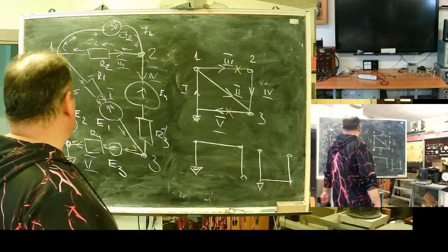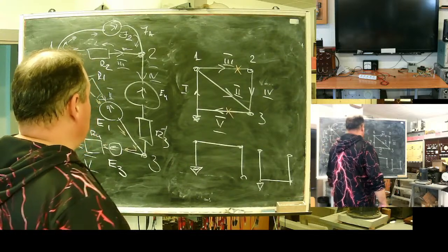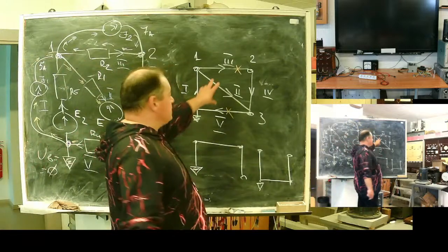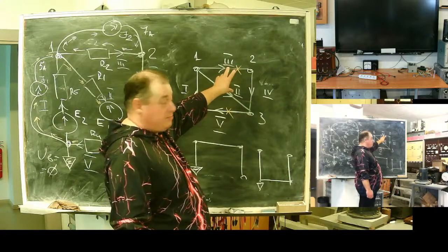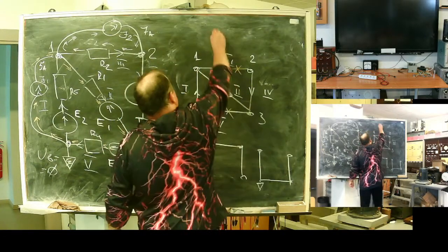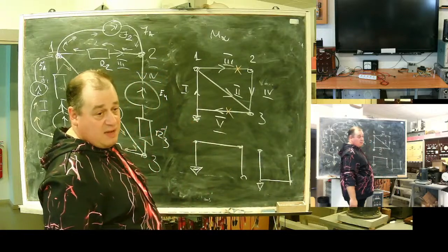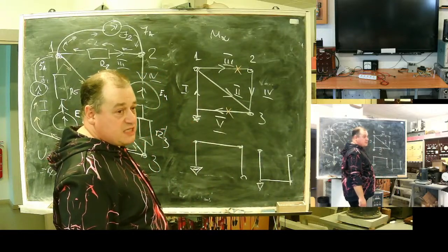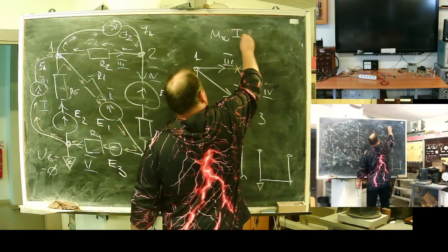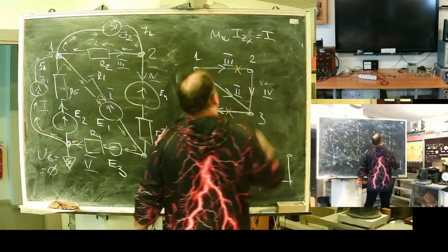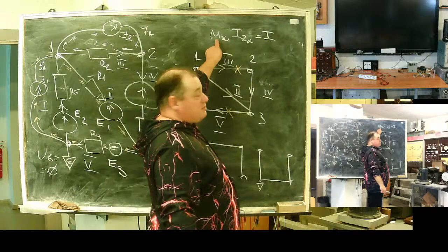To keep my graph connected. And here is one important moment. Actually, this graph represents some form of reduced schematic. This schematic can be described with the first incidence matrix M, and this matrix will be square. This means that M alpha equals I is a solvable system. This matrix can be inverted.